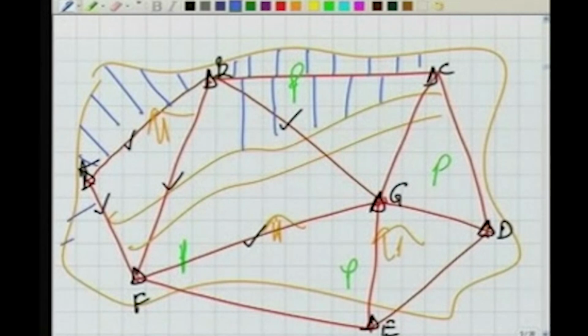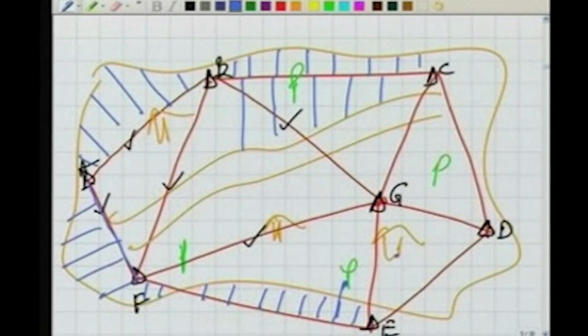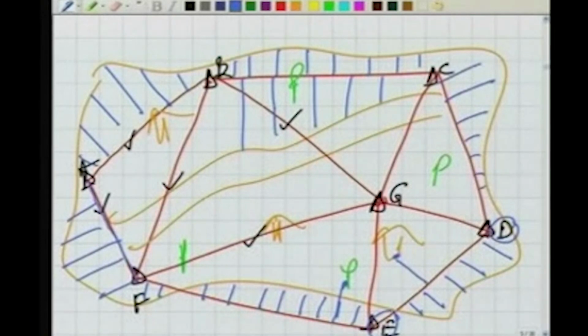For the boundary here, I can use the line AF. For the boundary here, I can use line FE. Okay, take the offsets. This tree can be plotted with respect to the same line here. This house can be plotted with respect to the line ED, and also this boundary. Similarly here, we have taken all these observations, and in our field book, what will we have?